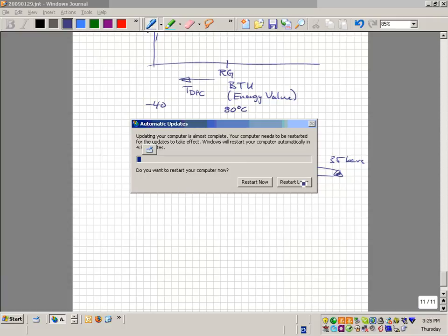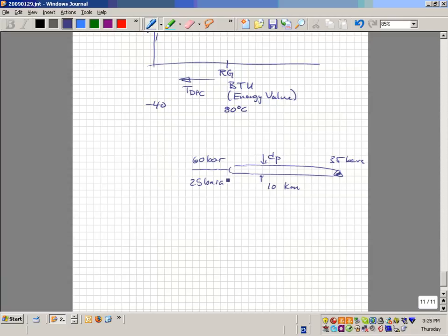Then, to get this to 35 bar, you're going to have to boost this up, okay? And once you're boosting it with compression, then maybe you can get a different diameter pipe, smaller, lower cost, and boost it up to 90 bar. Okay? So now there's an interaction between the compression, both the cost of the compressor, the fuel consumption, how far you boost it, and the diameter of the pipeline. And all of a sudden you get this interconnected model.